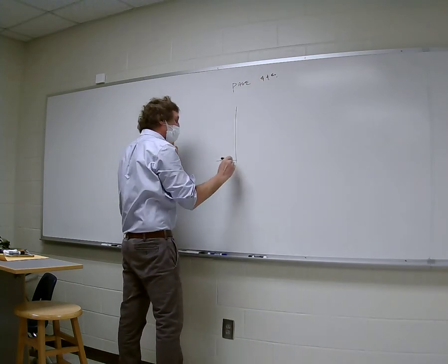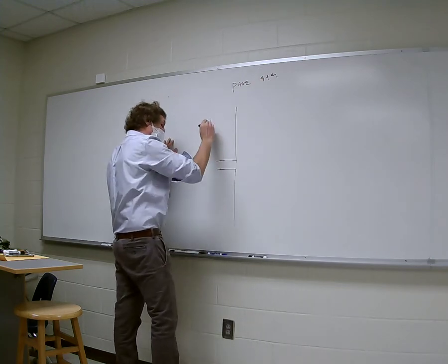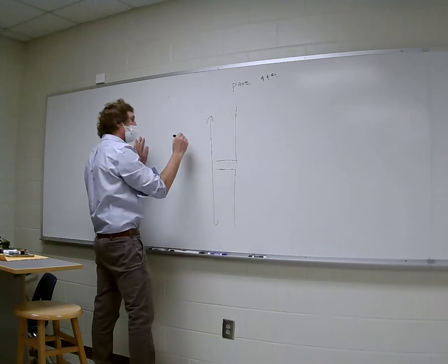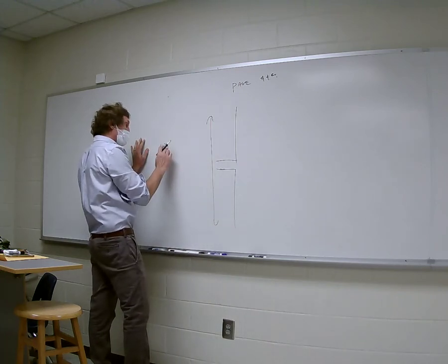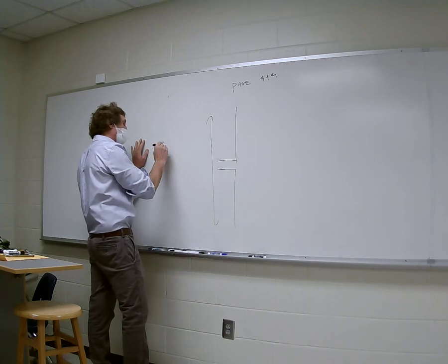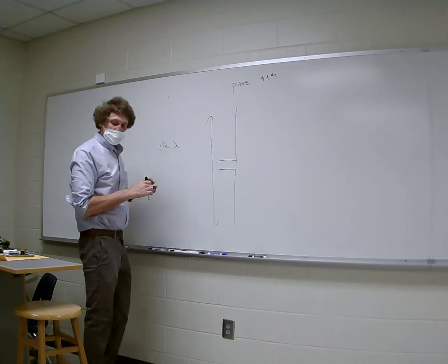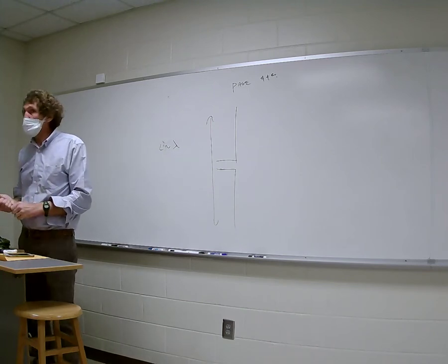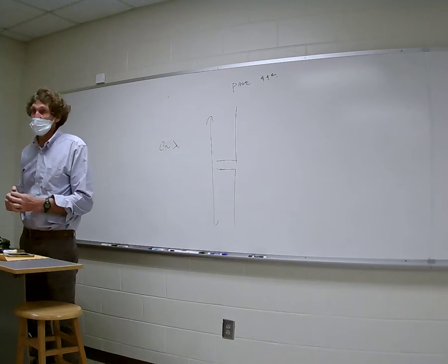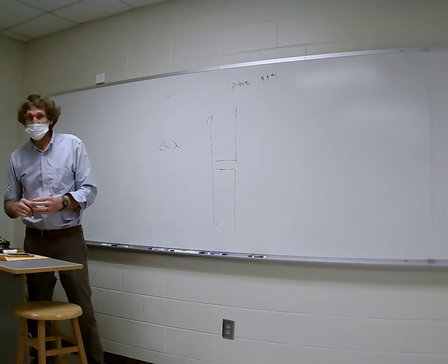So this is going to be, again, a straight wire antenna, but now the length of this, L, is going to be of the order of a wavelength. It could be a half wavelength, it could be 3/2 wavelength, but it's longer than a tenth of a wavelength. Got that? We're still in free space.